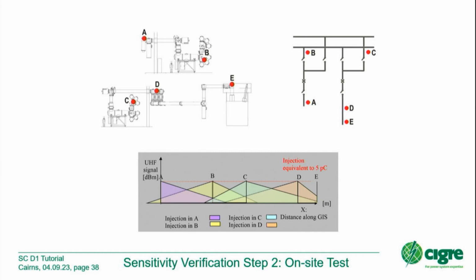We did some work with the supplier afterwards, and I don't believe they looked at what the magnitude was. They determined that the frequency was about 40 megahertz. Okay, maybe this belongs to the test setup. We can discuss this in detail. As a general rule, I cannot say this is a typical situation, because if there is PD and you have a typical GIS and a typical PD instrument, then you have a more broadband signal from that, and you will not have an overshoot resonance of 40 megahertz. So I will not accept a statement from the manufacturer.